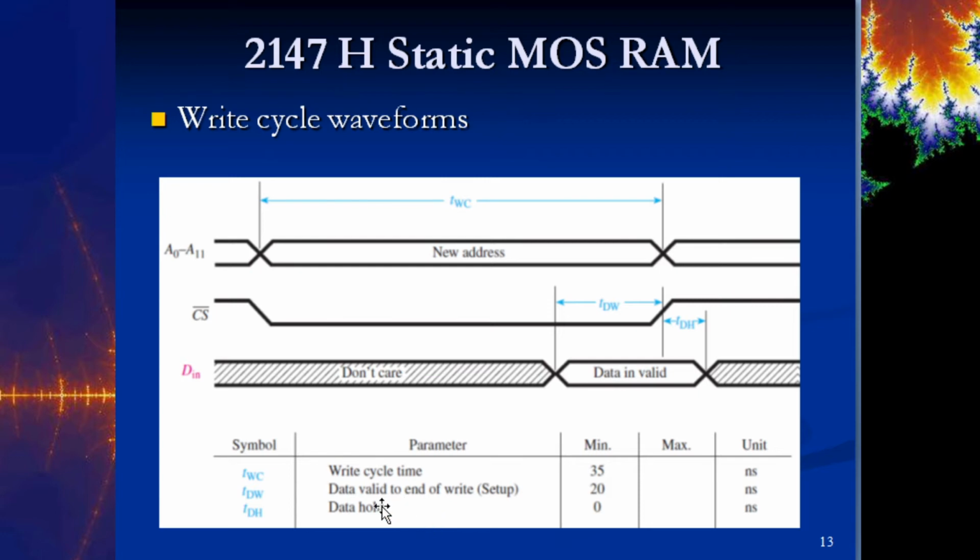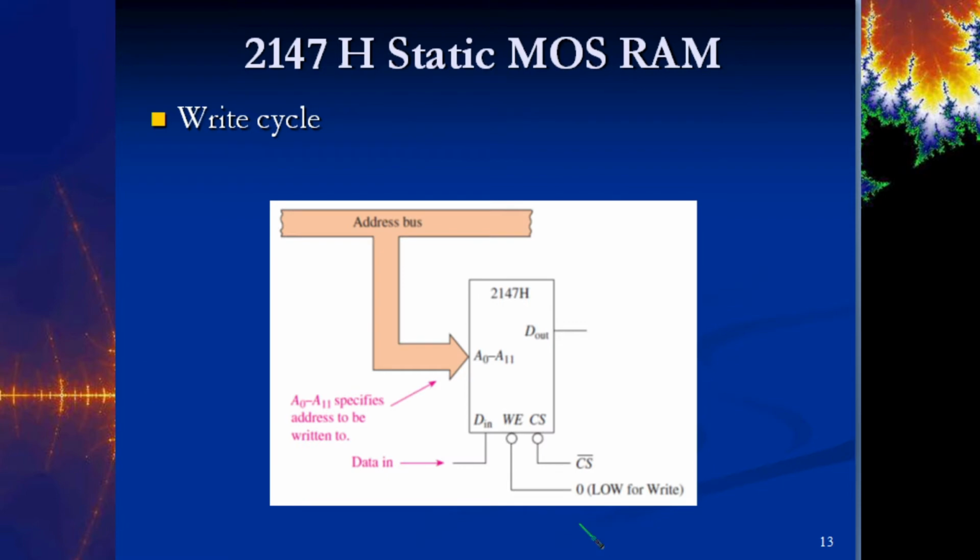And as we've said before, we talked about the hold, when we talk about the setup time and the hold time for a digital signal through some input or output. In this case, we have a hold, but it's at 0 nanoseconds, and that's typically where it is, and it's typically negligible. But just showing a typical access here. So here's the entire write cycle, and here's the address on the address bus. The chip select had to have been low.